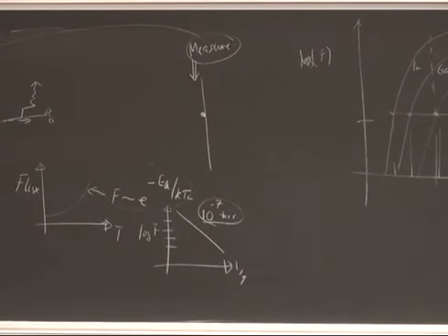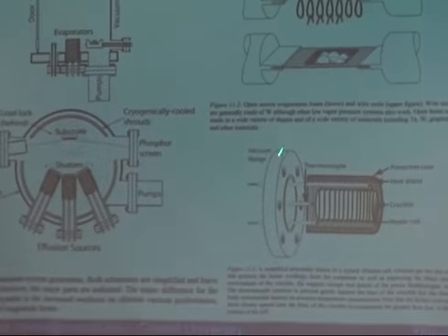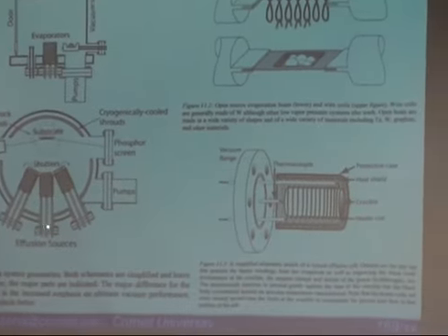There are many other sources. So this would be a typical molecular beam epitaxy source. You have this PBN sort of crucible. Here's the thermocouple, all right, and then these are the wires, the heater coils going around it. So passing a lot of current through it, a few amps typically, and then you're pumping a lot of energy into it. And then it melts, and then you have this. And then this is basically a flange.